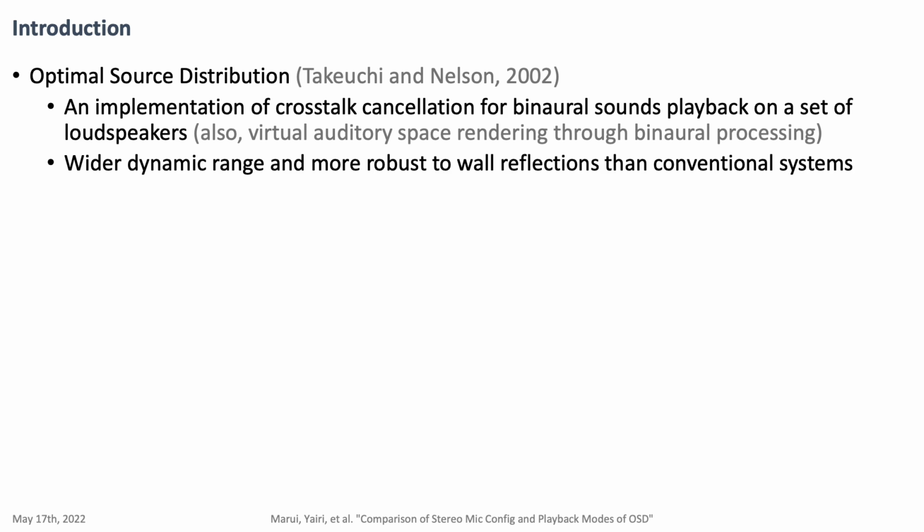So, what is optimal source distribution, OSD in short? It is an implementation of crosstalk cancellation for binaural sounds playback on a set of loudspeakers. OSD has wider dynamic range and is more robust to wall reflections compared to conventional crosstalk cancellation methods. It can be used for enjoying binaural contents as well as virtual auditory space rendering through binaural processing.